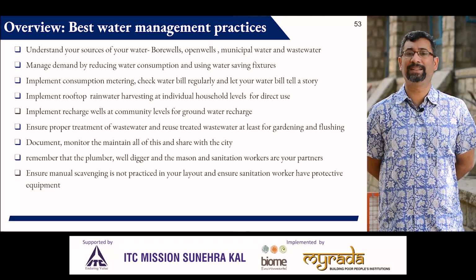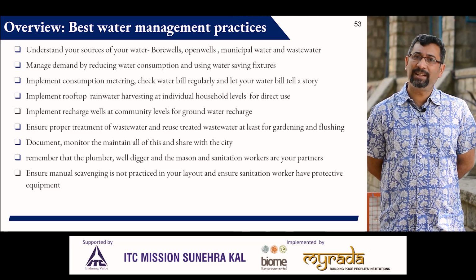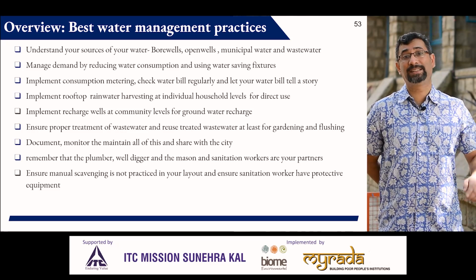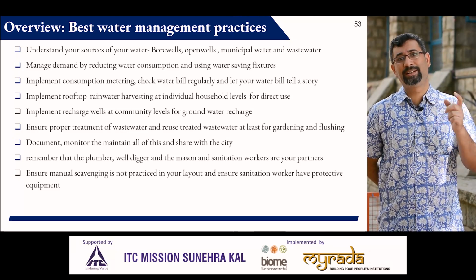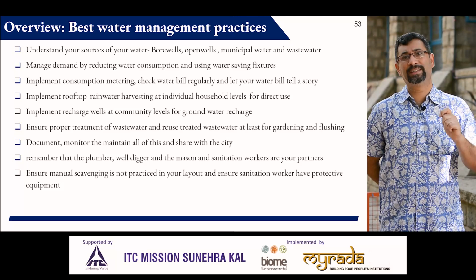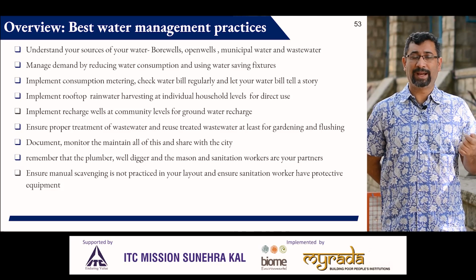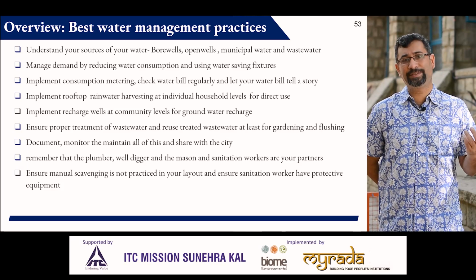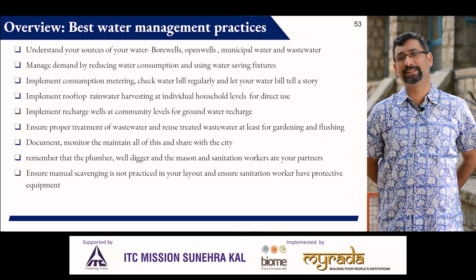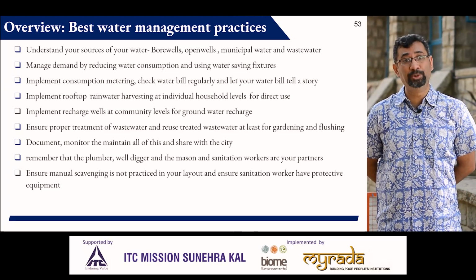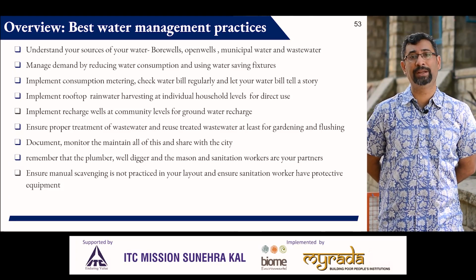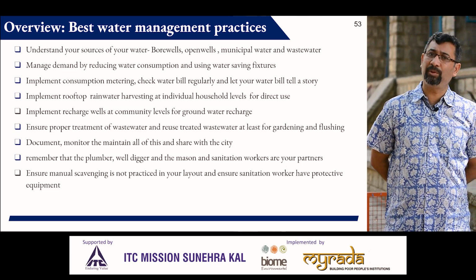So metering, and then setting appropriate tariffs and setting volumetric increasing block tariffs, meaning that everyone pays based on how much water they are using, and you are recognizing that the first n,000 liters, which you can decide for your own community what that n,000 liters should be, is what everyone needs to use.